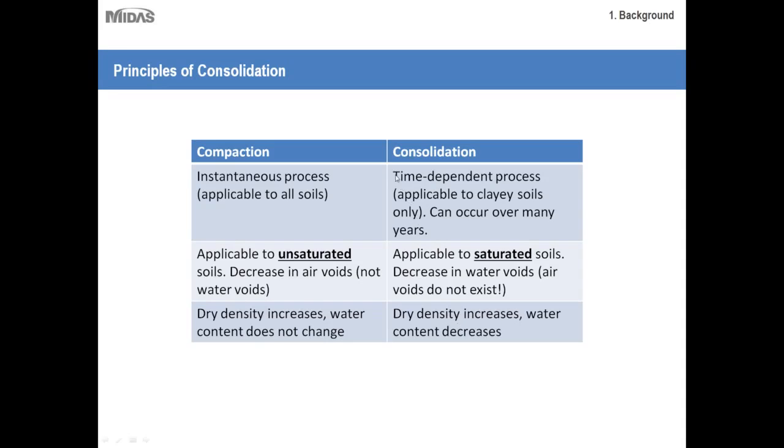So that's the main thing to remember about the differences between compaction and consolidation. First and foremost, compaction is instantaneous and immediate, whereas consolidation is drawn out over several years. In compaction, water doesn't play a role, whereas in consolidation, water is very key. It's a very important role.